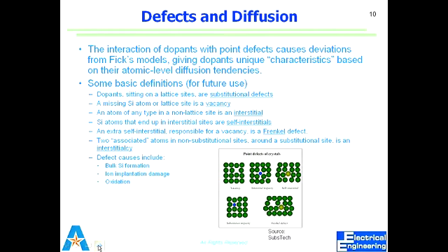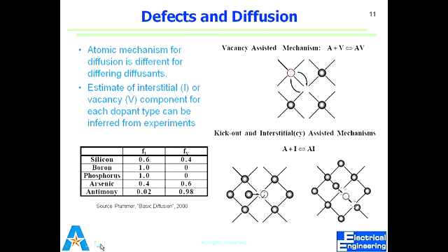How do we get rid of these defects? Heat it up and let it find its place. Give it enough energy so the atoms can find their energy minimum and settle down. These defects can arise during the silicon formation, implantation, or oxidation. So all of these can happen because of that.